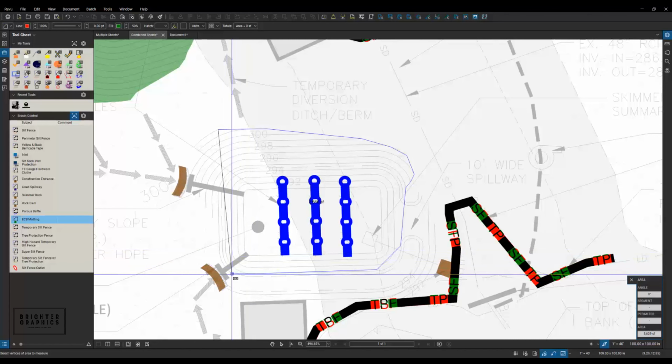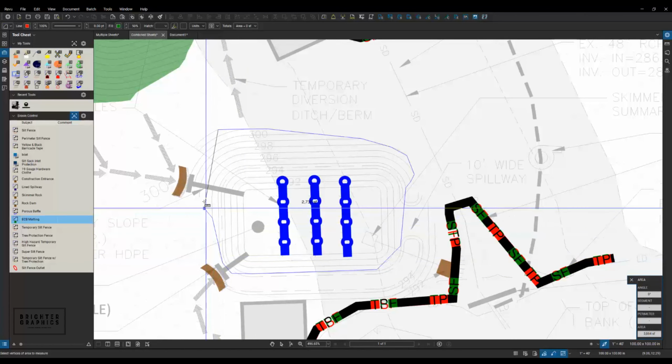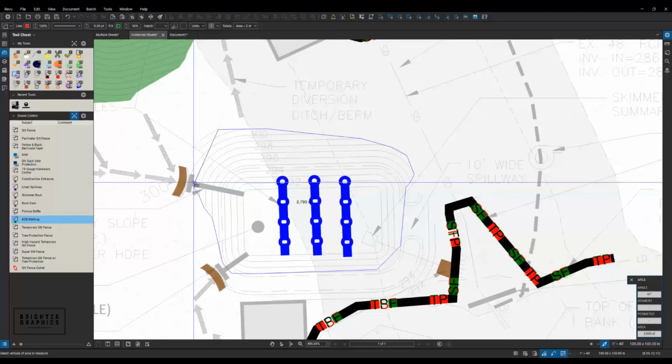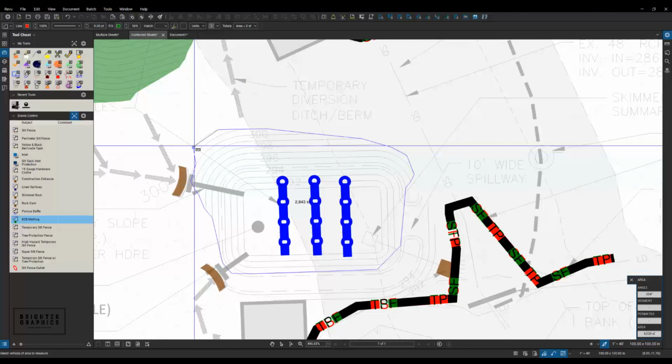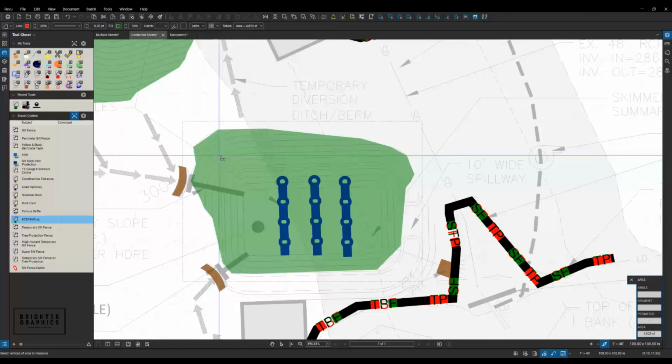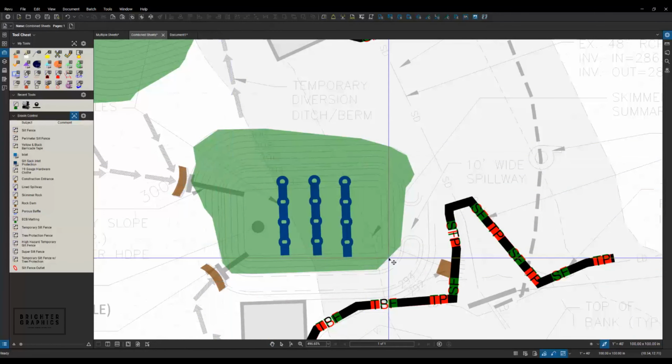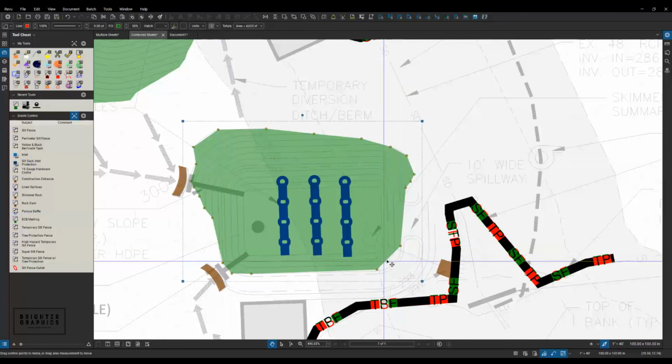And I'm going to come out to here, work my way out again, doing the best I can to cover this area. And double click when I'm done. And it covers that. Now I would come back, select this. In that curved area, I can right click, convert to arc, and it fills out that corner a little bit better. So I would clean up these here.